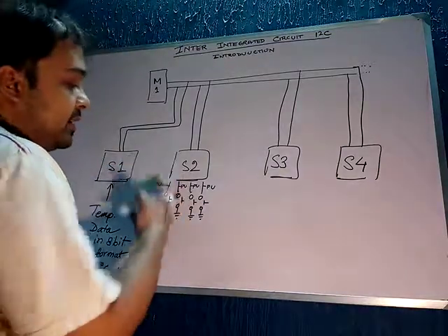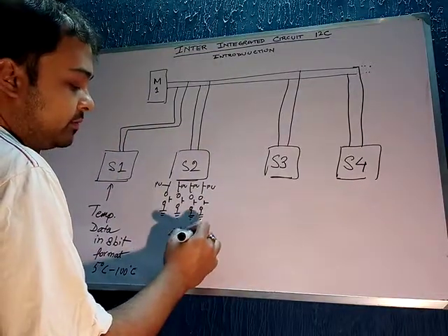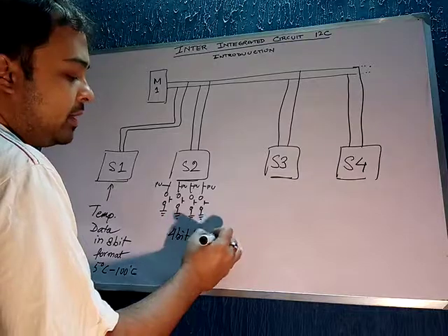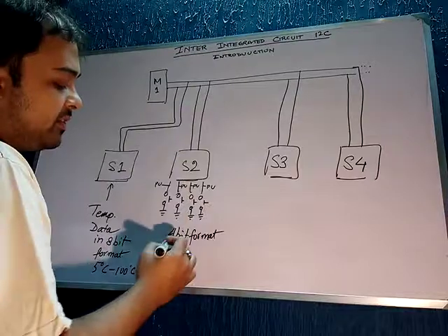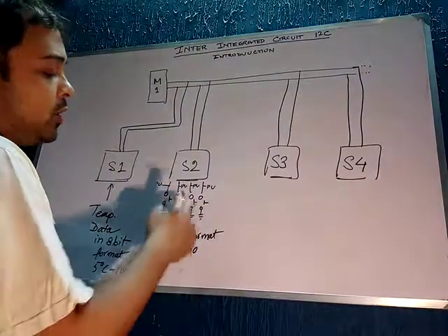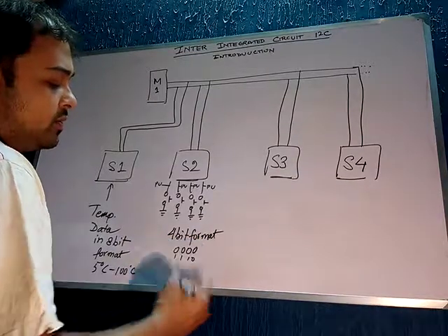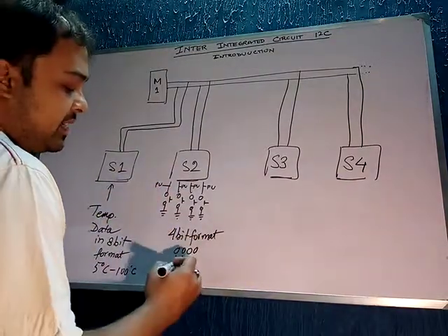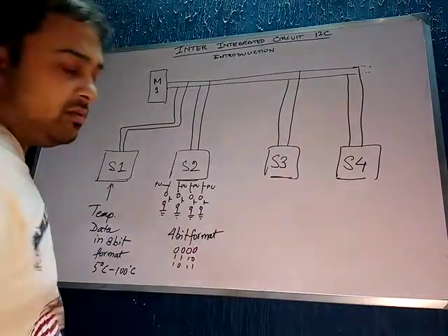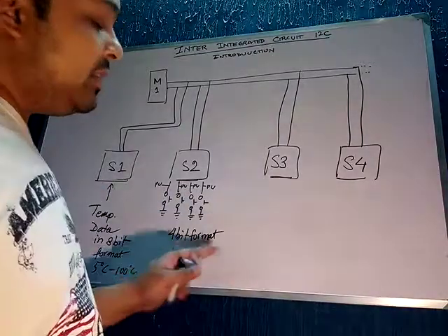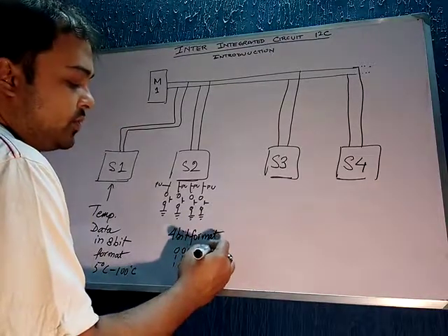So this particular system has a 4-bit format, because when all the buttons are pressed it can send a data of 0000. When only one button is pressed, it can only send a data of 1110. When this button is pressed, it can send only a data of 1011, and so on, right? Now you can tell me, what about the other 4 bits? Well, you can just pad it as 0000.